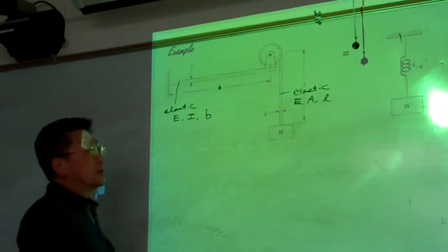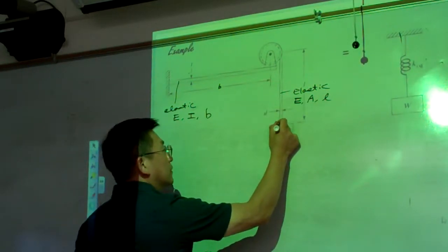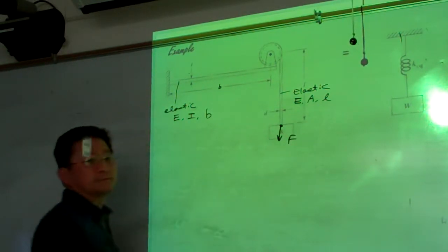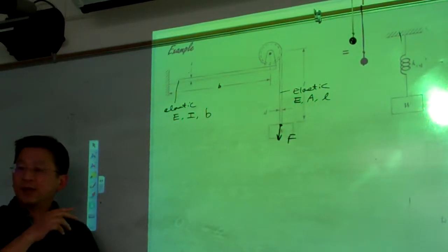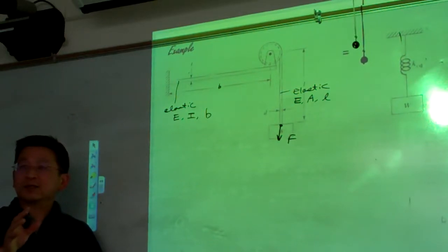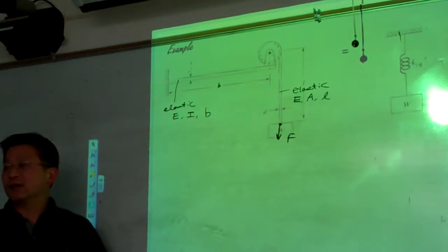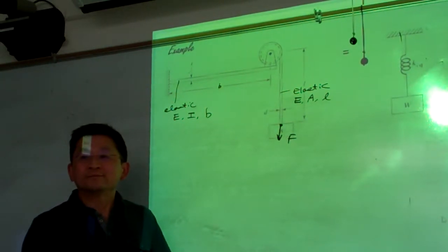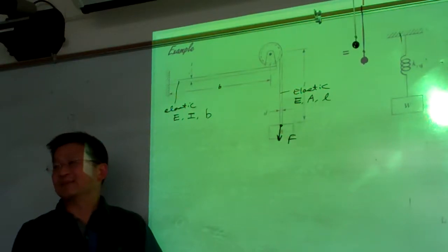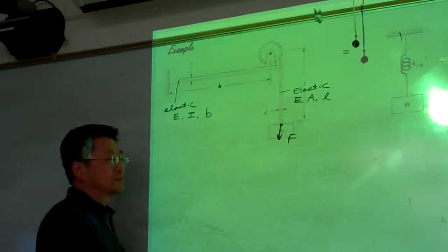This represents the loading here. The first thing we need to tell is whether this system is in series or in parallel connection, because the different cases have different formulas. That's the first step. So which one? Series? Why? Yes, the answer is series, because the force transmitted through both is equal.